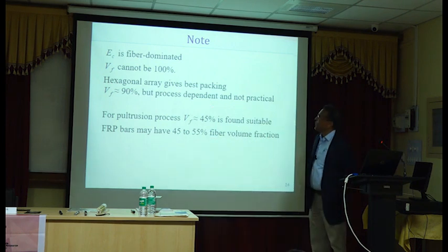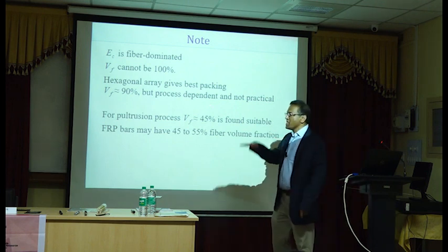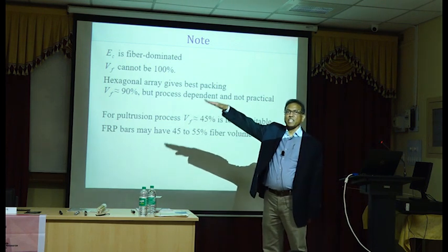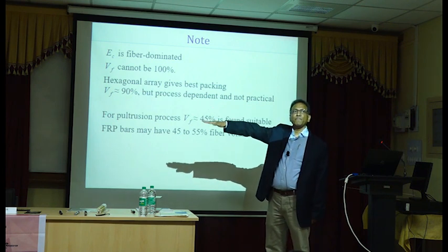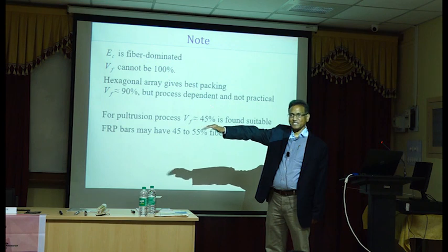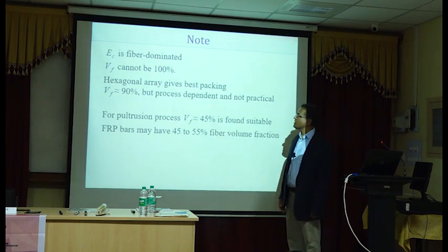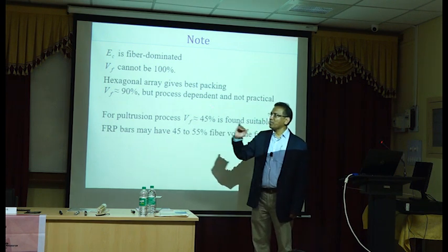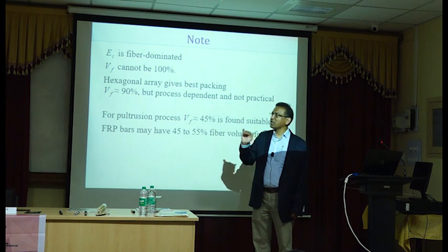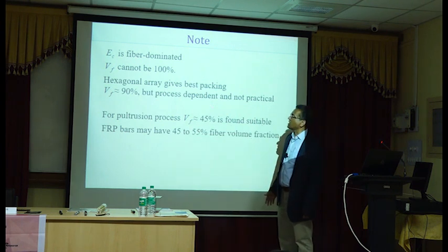All right. So, what do you see from that equation? What you see is, in the direction of the fibers, the properties of the composite are dominated by fiber properties. Does it make sense? Makes perfect sense, because fiber has its main strength, or primary strength, only in the direction of the fiber. In the other direction there is no strength.